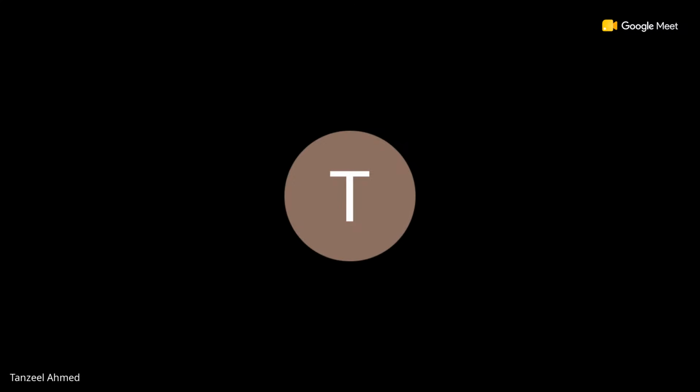Yes, sir. You have to do that for each of the output pins. There are 4 output pins in your IC, so you need to do that for each of those and plot it against the clock signal for each of them, so you can directly compare over there. 4 plots, 1 plot per output pin, clock versus output pin, like that. Clock versus QA, clock versus QB, clock versus QC, clock versus QD. The LSB and MSB I'll put in the G space. I don't know how I forgot about that.